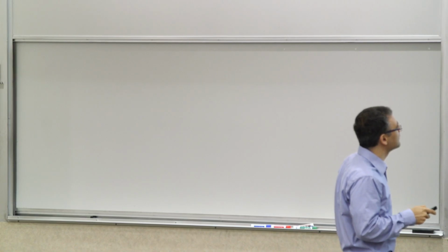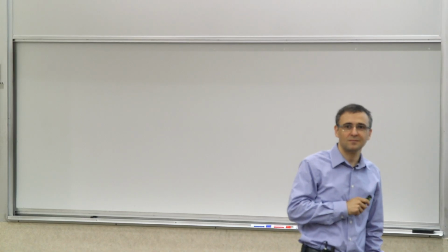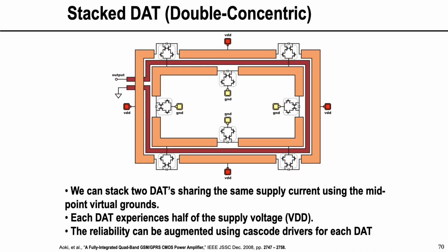Because you look at the VDD. The VDD is for the outer primary, those 4 points. Now, the ground for the outer primaries is the common source point of these outer differential pairs. This normally would have gone to ground at this point. But now, instead of going to ground, it's serving as the VDD of the inner primary loop. You can see that the ground of these pairs, these cores, is basically connected to the midpoint of these inductors, the slab inductors of the inside primary.